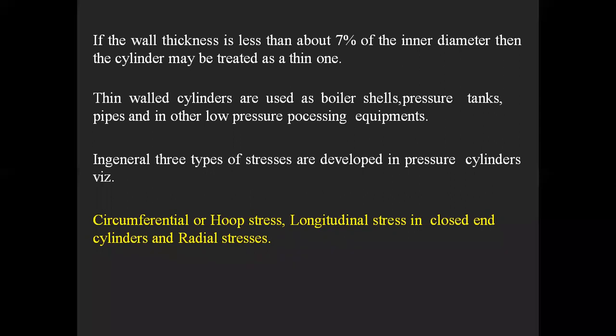And next, thin walled cylinders are used as boilers. They are used as boiler shells, pressure tanks, pipes, and in other low pressure processing equipments. Wherever the pressure is very low, we can use these kinds of thin cylinders or thin walled cylinders.